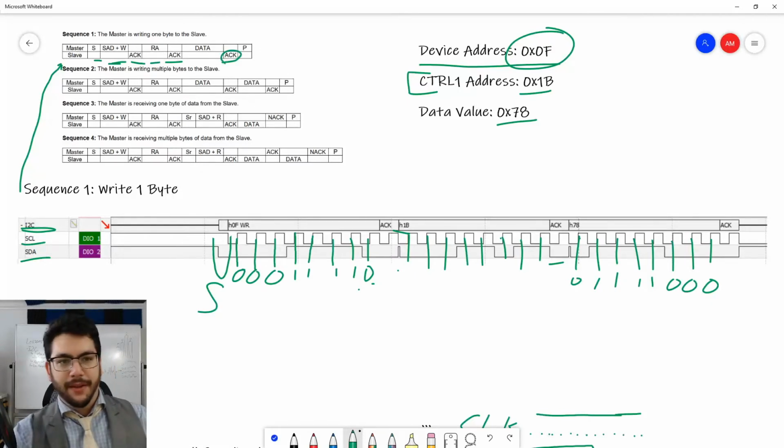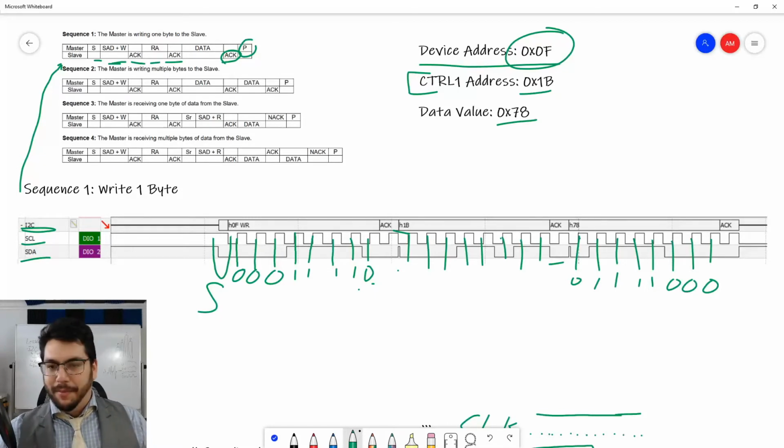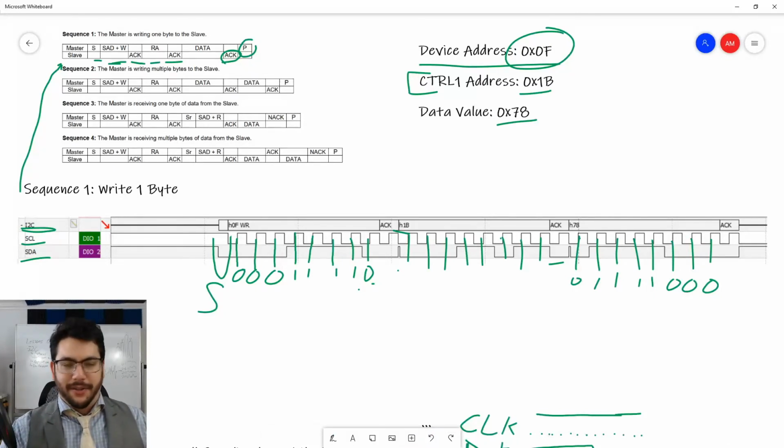And there's supposed to be a stop bit. I don't know why I didn't send it. I might have forgot to put that in the software, but there's supposed to be a soft stop bit. And that might explain why some glitches were happening earlier. So there you go. That is a read operation. Or sorry, that's a write operation. A write operation is very straightforward.